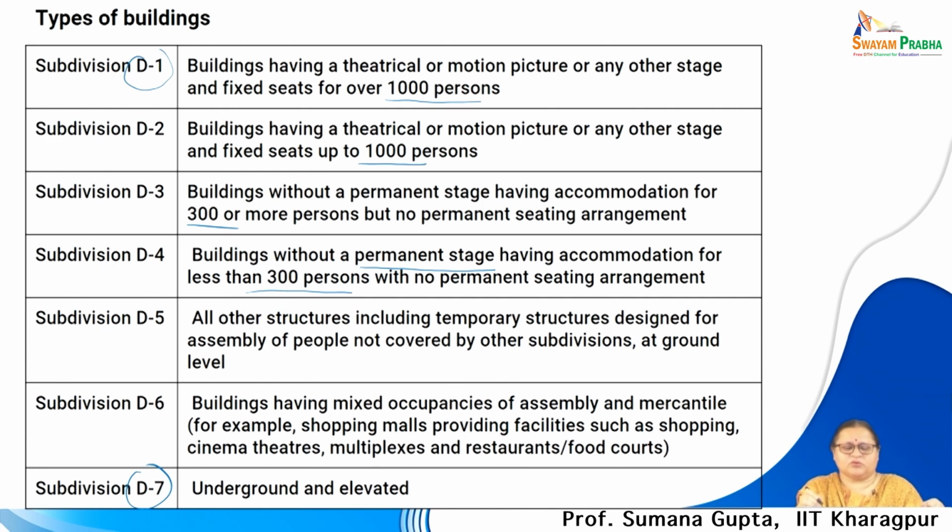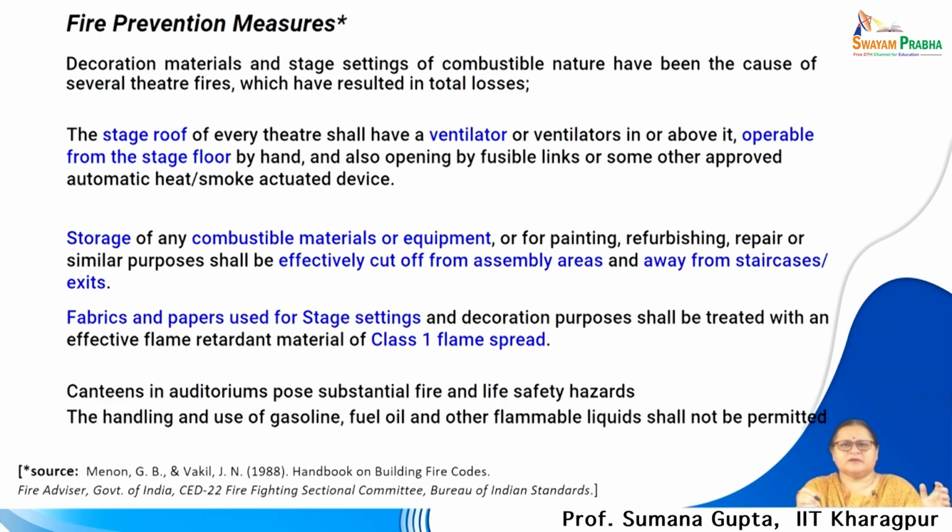Now, all these buildings which are made for a purpose of public gathering must be having what other criteria that has been discussed so far in my previous modules, that they should have the provision of materials which should be fire rated. Here also we will see they should not have any toxic fumes spreading due to burning process.